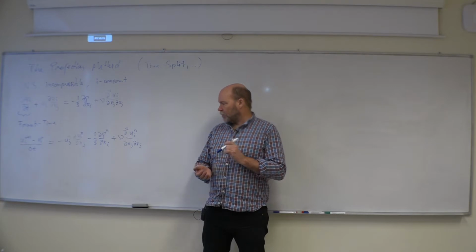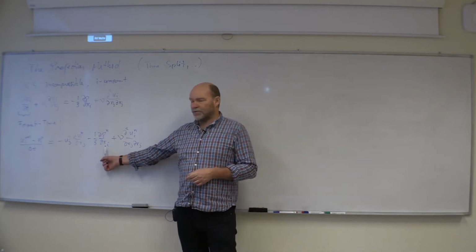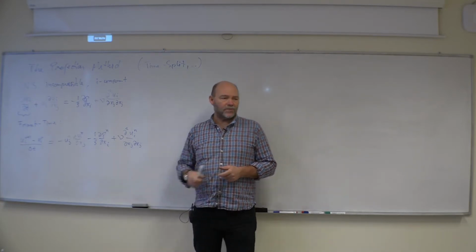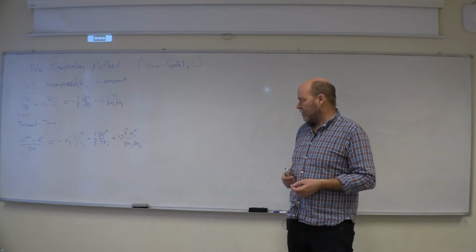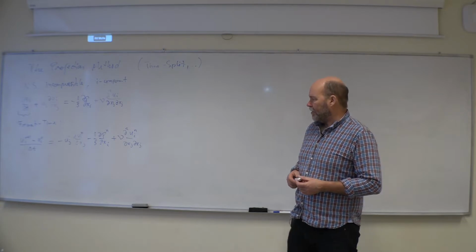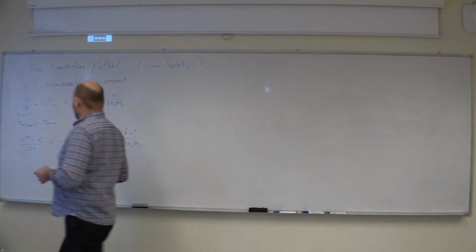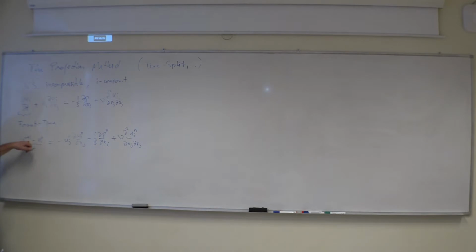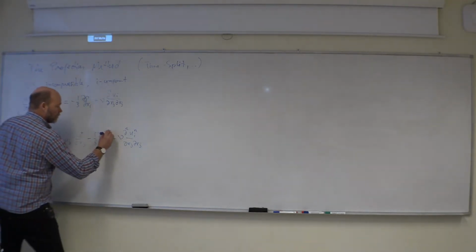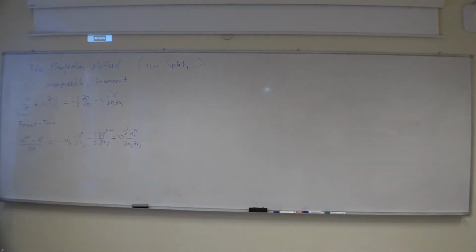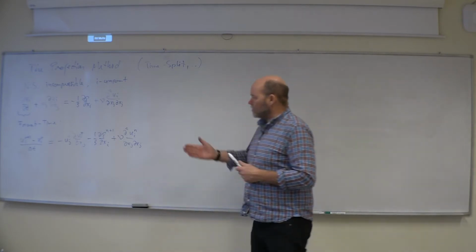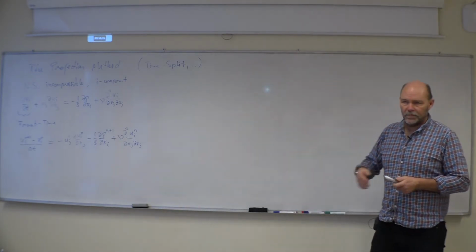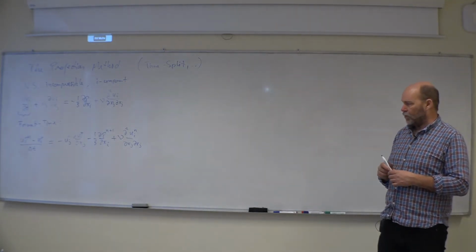The reason or the problem is the pressure. We don't have any equation saying time derivative of pressure. How do we update the pressure? That's the pain. So to have this one more correct, the new velocity has to be based somehow on the new pressure. It should be plus 1 there. And that is the pain. This is one equation with two unknowns. That's impossible. We are missing one equation.